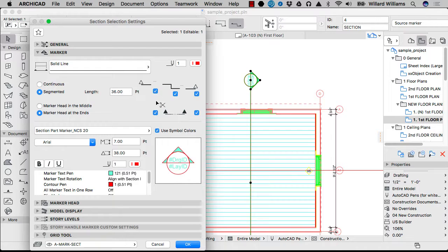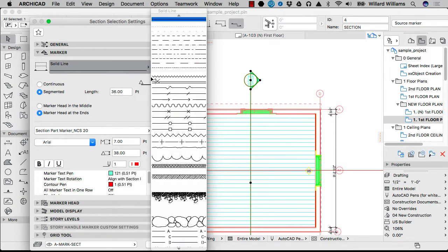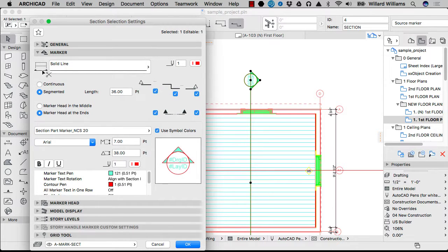I can have a segmented line so that I have a head, two heads, and a kind of a middle body. I can adjust what that line looks like if I want it to be dashed or a crazy stone thing. I can adjust what that middle line is looking like. I can also adjust what the pin of that line, going across between the different heads, looks like.